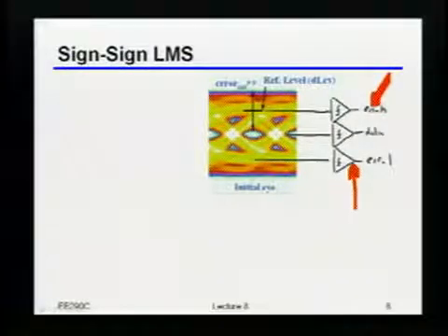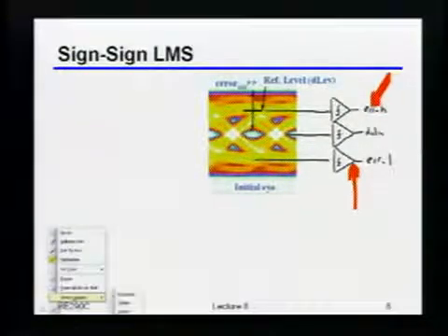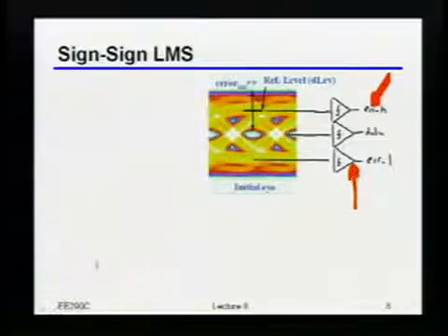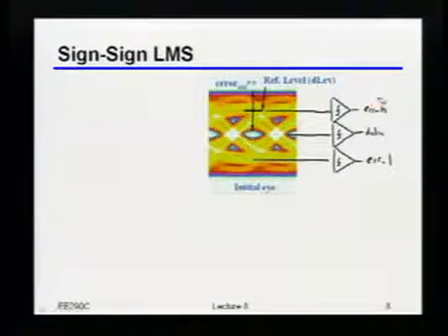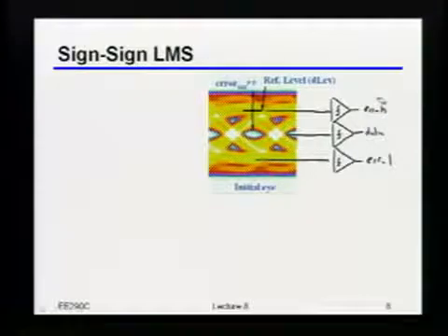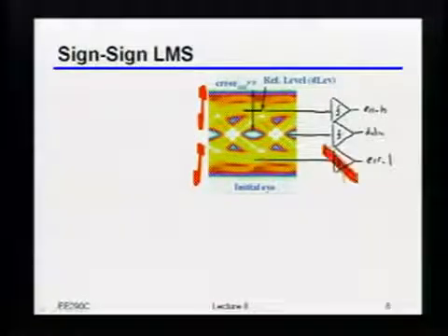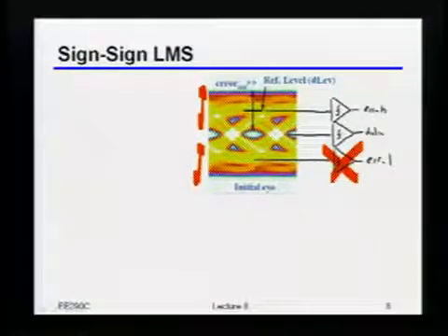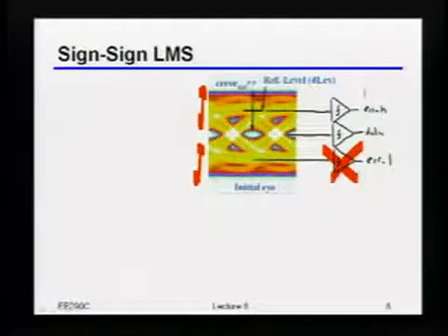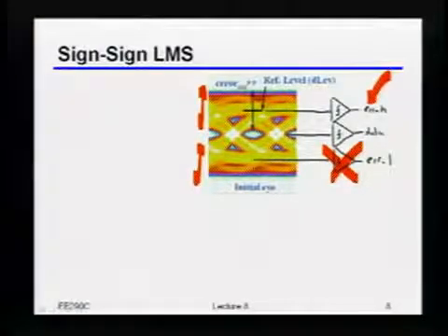Okay, yeah. So basically, what you will indeed occasionally do is you'll just say, well, you know what? As long as everything is reasonably linear, there's no really extra information in the errors around here versus the errors around here, right? So what I can basically do is just throw out one of those comparators and then only do updates when I actually have valid error signals coming out of that upper comparator.